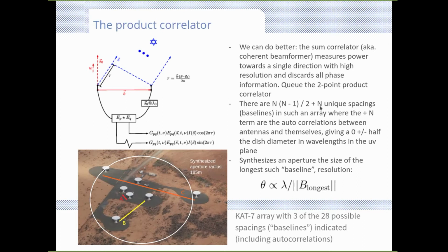So there are n such autocorrelation products. That typically correlates, for instance, the low noise amplification circuitry within this antenna with itself. So we get coherent noise from our measuring equipment. So typically we discard those measurements because those coherent noise measurements don't scale down with time.